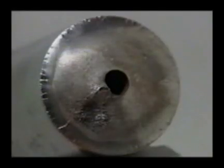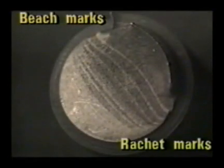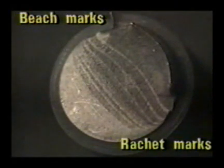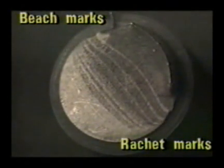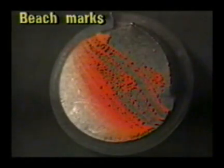Since high cycle fatigue occurs very slowly, the surface texture is quite smooth. The color is a light silver gray in steels, since the fracture is smooth enough to be reflective. Prominent surface features called beach marks and ratchet marks are often found on fatigue fractures. The location where the crack starts is called the initiation site. A beach mark is formed when a fatigue crack changes speed. If there is no change in speed, beach marks will not be seen. Also, beach marks may not form in hard materials.